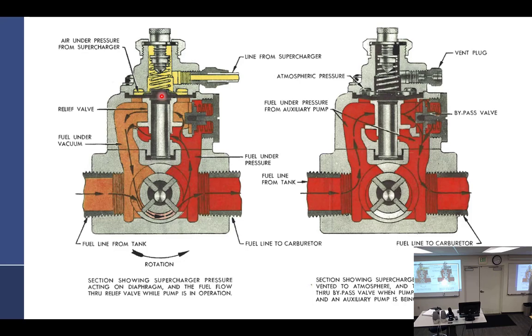So this nut right here, as you turn it to the right, it goes down, putting more pressure onto that spring, which puts more pressure on the diaphragm. It's still righty tighty, but just for the spring, not for the nut. If you can remember nothing else, remember this: when you turn that screw on the top to the right, you increase the pressure. And when you turn it to the left, you decrease pressure.